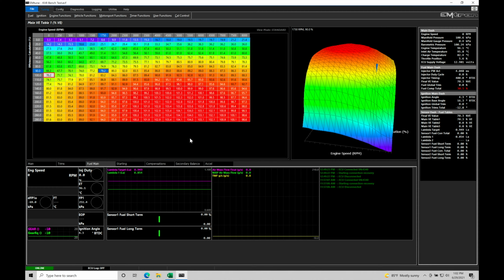If we're dealing with a race engine where it might have a simplified pattern, we might be retrofitting an aftermarket cam and crank trigger setup. We'll find that those specific details can also be programmed into the Emtron, but we have to be paying attention to a lot of specific details in order for the Emtron to recognize the patterns properly, as well as the signal type from the sensor that's going to be picking up the actual pulses coming from the cam and crank trigger wheels. So we have a lot of little details here to cover.